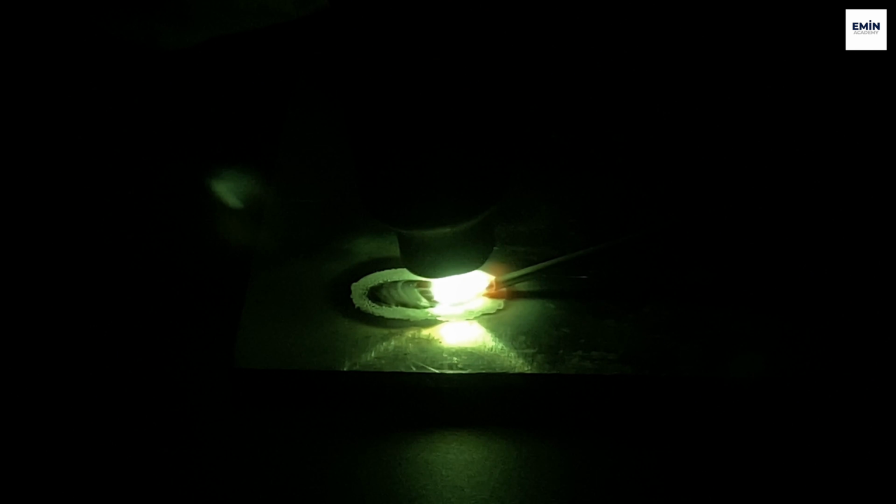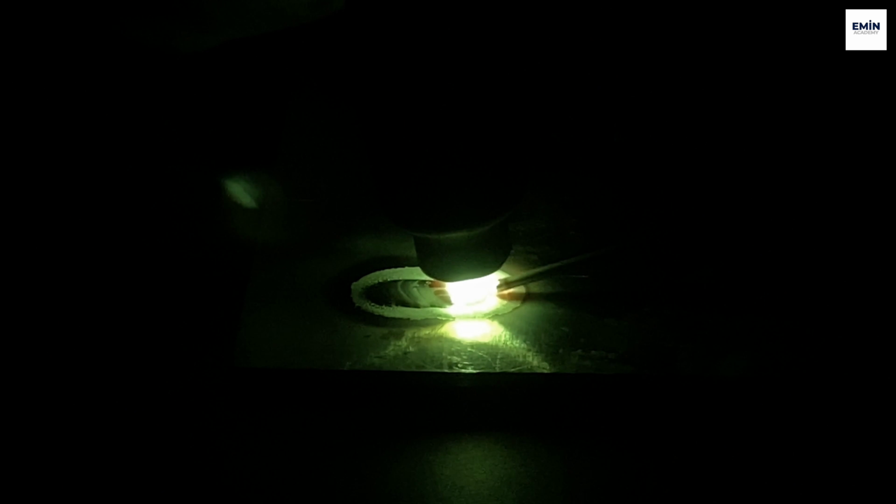The biggest advantage of alternating current is the oxide cleaning effect. The aluminum oxide layer on the aluminum surface has a very high melting temperature. In direct current, this oxide layer does not break. In alternating current, the oxide breaks in the electrode positive phase and penetration is achieved in the electrode negative phase. These two effects work alternately.